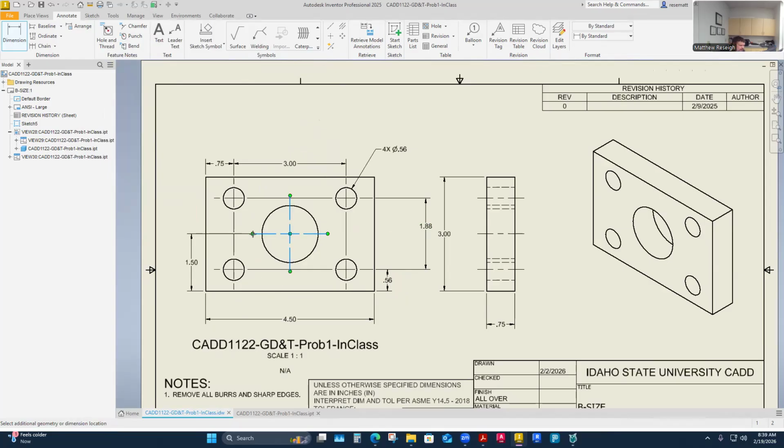Yeah, and I'm going to pull the center line out to the object edge though. I know that was easier to see in CAD, but here I'm just going to try to pull the center line to the object edge and let my dimension go to it. It does create a little gap here. Usually, maybe in an ASME standard, it would be okay to have those overlap each other and not show a space off. But when I pull that out, it's going to kind of snap my dimension off, which I'm okay with. So I think I'm going to use that one, and I'll just drop one down here in the lower right here.